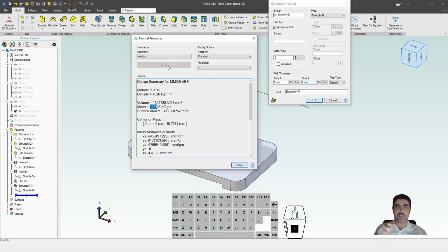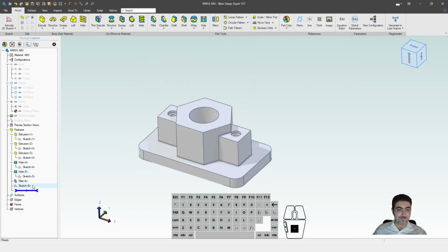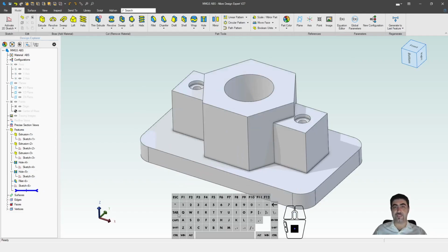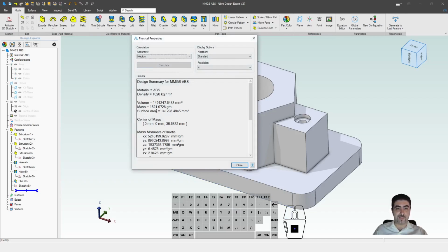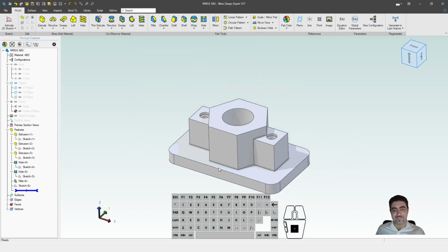And to prove to you that this works, right? Here's my sketch. Now I cancel the extrude. I hit Escape and cancel the extrude. I hit I again. I calculate, and the mass is larger. Right? It didn't cut it, so the mass is larger now. So that's a tip that I didn't use in the leaderboard entry, but you could use it if you go for it yourself.